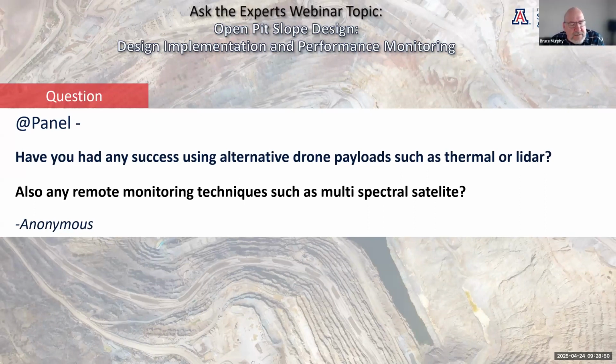Yeah, just a comment from my side. Just all the things related to rockfall or any movements, besides the radar and scanners and those kinds of things, drones are actually allowing you to do a lot of change detection, sources of rockfall. It's all kinds of things. It's really a fantastic tool for us to use. You know, all those LiDAR capabilities that we get out of it to actually look at how those slopes are changing over time are fantastic properties for sure.